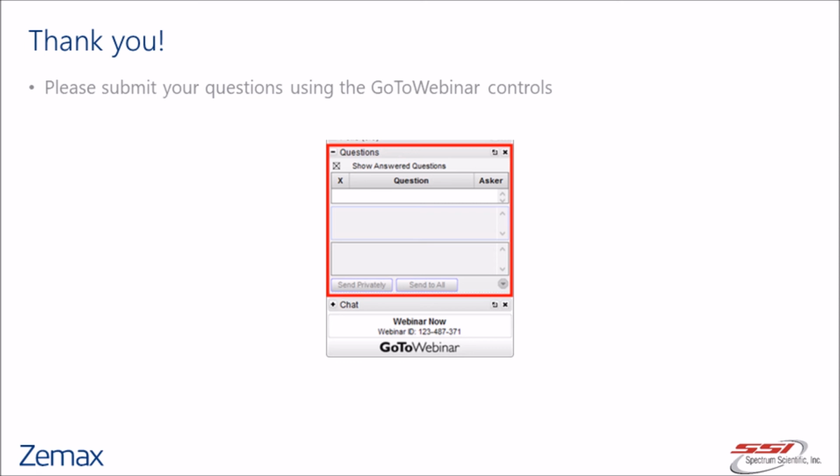So there's a question here, a follow-up to the best fit sphere question. Since only the Y coordinate is provided in OpticStudio, we can't necessarily directly provide the sag table to the fab house. Okay, I see what you mean. The sag table in OpticStudio just gives you one orientation. In the settings, you can change that orientation, so you can create the sag table over different clocking angles. So you might want to provide your manufacturer with these freeform parts, obviously with more than one sag table.